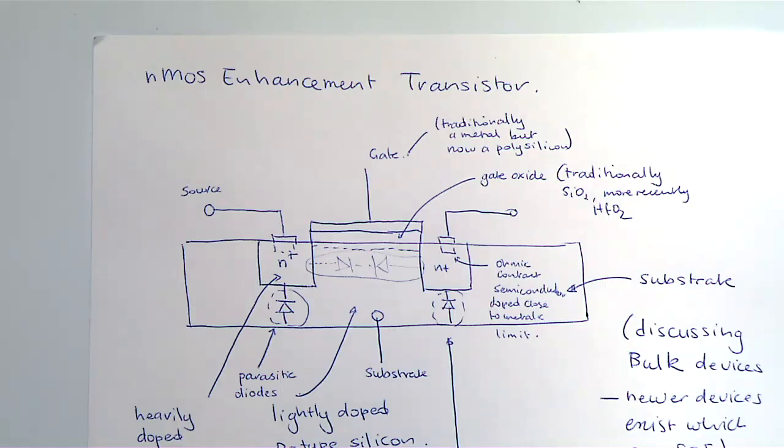That would be the size of your transistor. Usually the channel width's about 7. I've added a little bit in order to add some other stuff around it, and then a little bit more space because you might want a larger transistor that has enough drive. So that's your whole transistor.